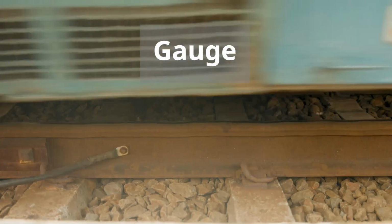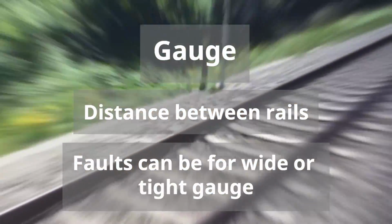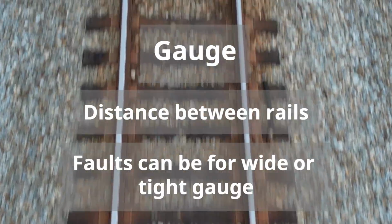Gauge. By using lasers to measure the distance between the rails, the train highlights areas of wide or tight track gauge. Wide gauge is more common and can be caused by base plate shuffle or failure of the housings in the sleeper, allowing the rails to be pushed apart under the load of passing trains.